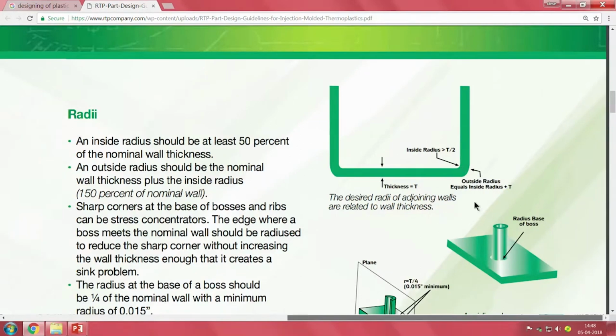But in the case of our printed parts, it just prints vertically. There is something which is stacked up and something which is there. There is no way of, see, this is printed and on top of it, now layers of this are printed. There is no way of building a radius here. If you build a radius, it will still be dependent on the resolution of the machine.